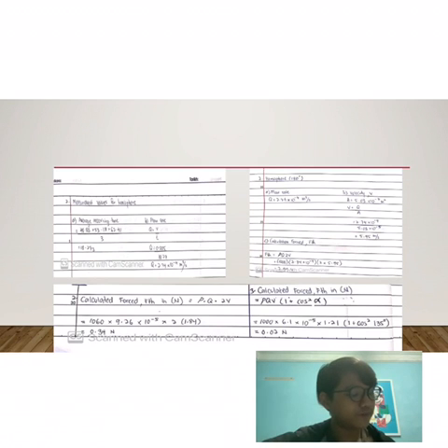A is 5.03 times 10 power of -5 square meters. And the V formula is Q per A. Q is the flow rate, 2.74 times 10 power of -4, divided by A, which is 5.03 times 10 power of -5, and we get the velocity 5.45 meters per second.